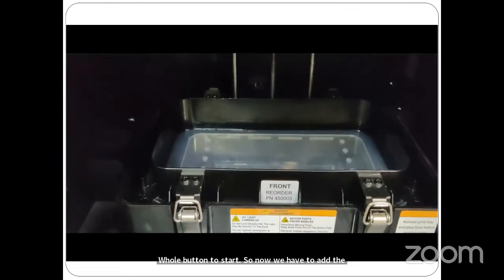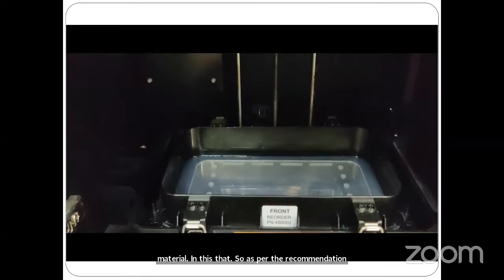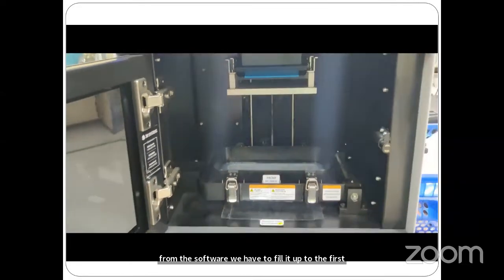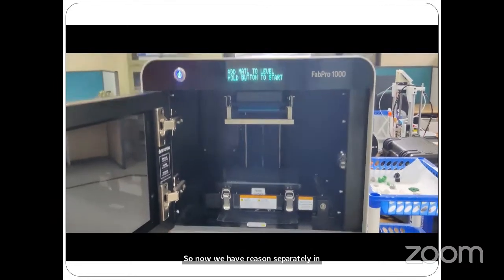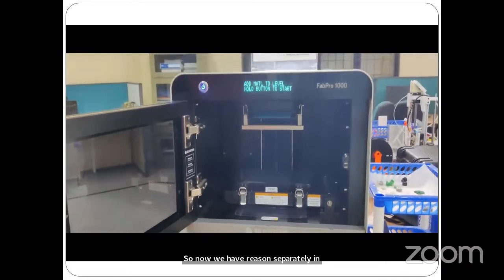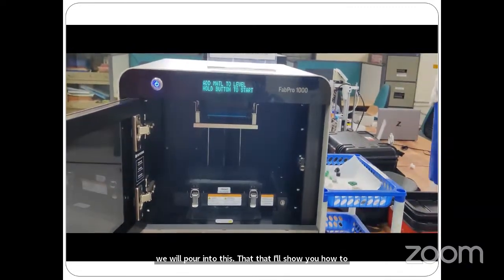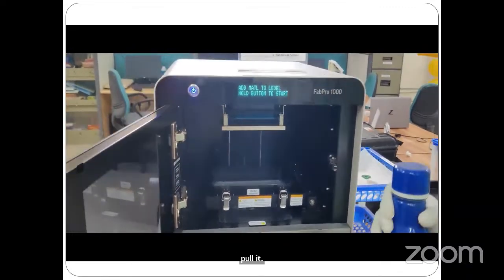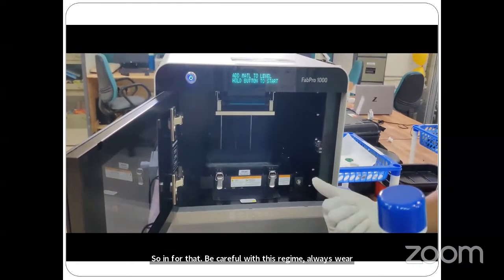So as per the recommendation from the software, we have to fill it up to the first level, that is the minimum level. So now we have resin separately in another bottle that we will pour into this vat. I'll show you how to pour it. So before that, be careful with this resin. Always wear gloves and a mask before doing this.